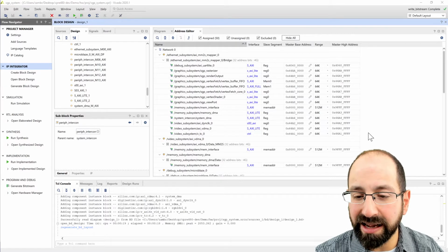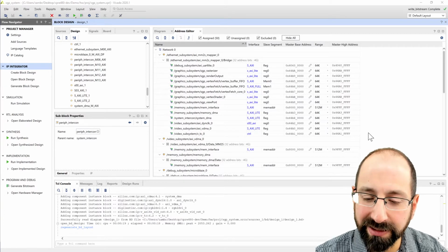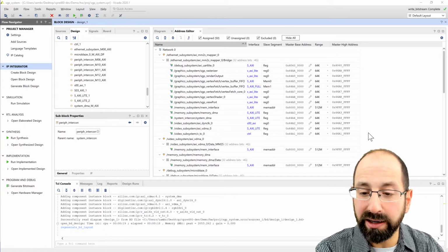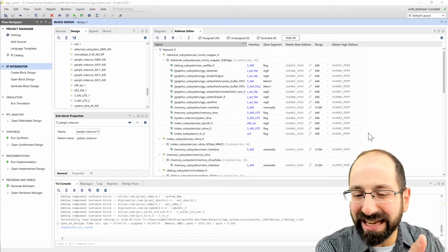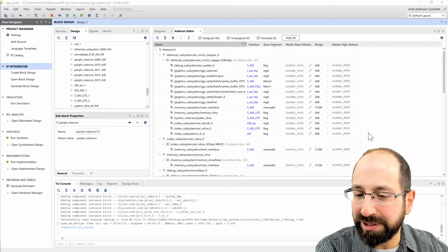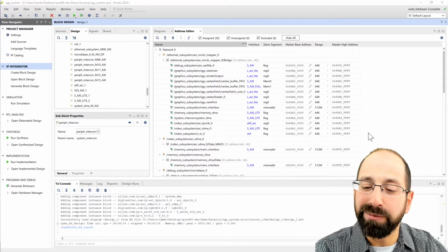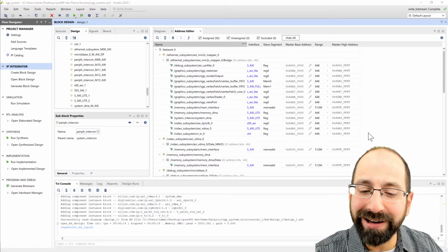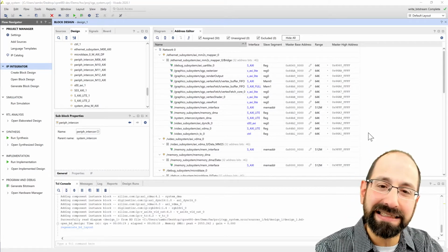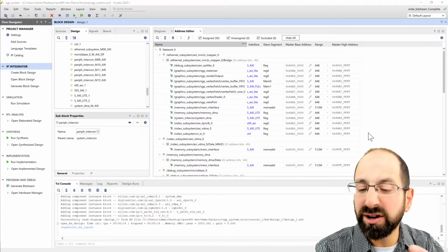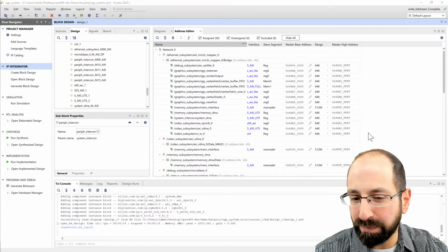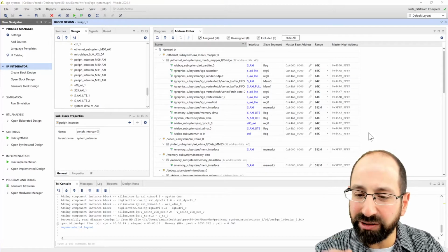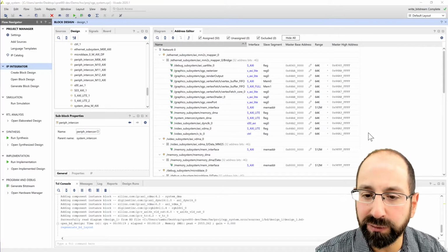All ARM-based designs, if you look at the bootloaders for ARM-based systems, including every one of your cell phones, that's a big part of the boot process: determining via a little text file and ultimately a binary blob what are the IP in the system and what addresses they are at. Right now, we do it via just hard-coding in SGP system.c and SGP graphics.c. There is a way to export a header file that basically #defines all these ranges for us. We didn't have a good way to integrate that cleanly into the rest of our driver infrastructure.